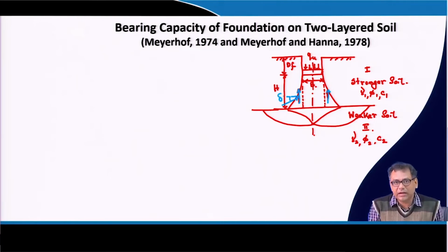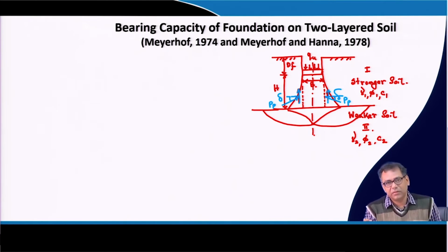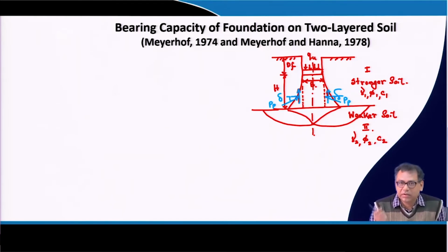Now, I am considering delta, later on I will change it. So, this is Pp and that will act in both the directions. So, at an angle of delta to the vertical to the surface, and the surface is this dotted line, you make a vertical line, and with that vertical line it is making an angle delta, because that is the case and it is common for your earthquake theories. So, if you read the earthquake theories, you know that this will act at an angle of delta.